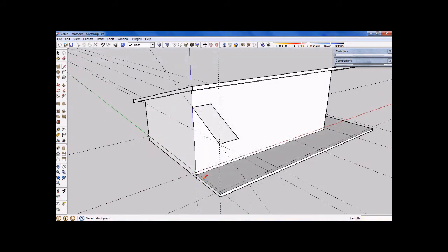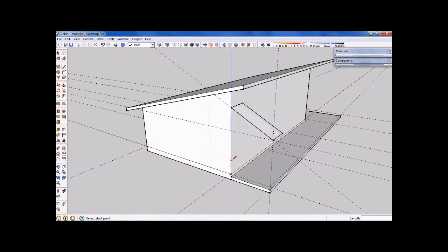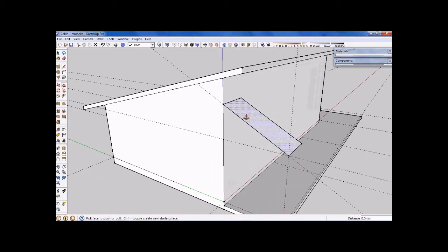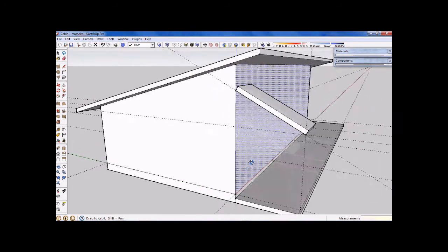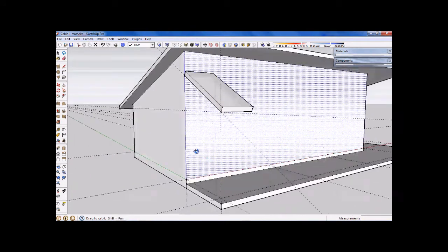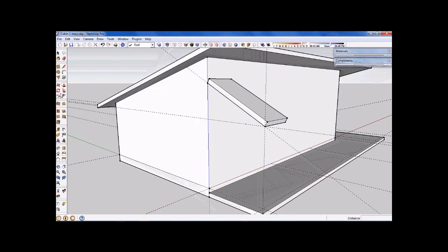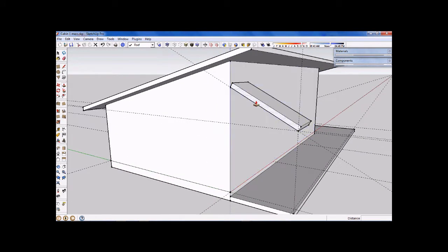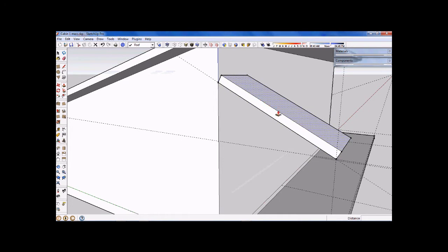so I can start creating this roof shape. We'll do something fairly similar to what we've done in the past now. I'll use my push-pull tool to push-pull that roof upwards, let it go anywhere, but then type 145, which is the dimension we used for the main roof as well. We've just got to plumb that roof up exactly the way we did in the last roof, but before we do, we'll need a construction line along this top edge of the roof. So grab your tape measure, click along that edge of the roof, pull away. Doesn't even really matter which way you pull, but type 0. You'll then get a construction line perfectly on that edge.